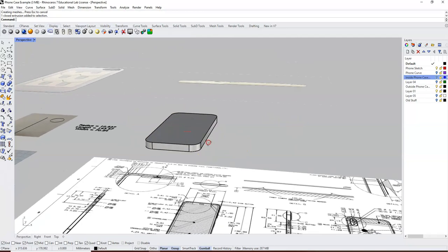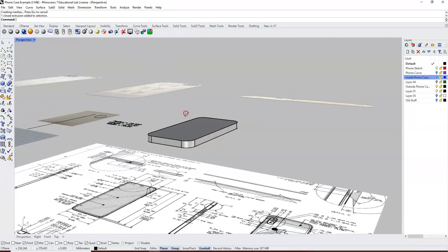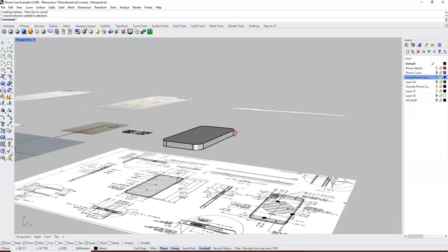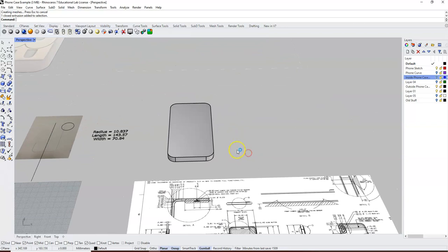So there's a variety of ways that we could do this. I think the easiest one is that we want to scoop out the insides of this and leave the wall thickness. And if we remember from the canoe tutorial we did together, after we made that canoe solid, to give the thickness of the walls, we used the shell command. So we're going to use shell. I'm going to type in shell in my command line and select shell.